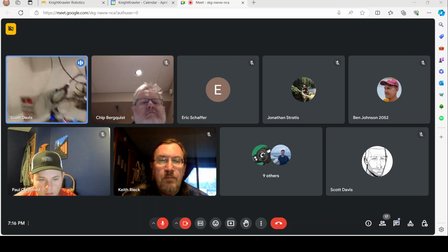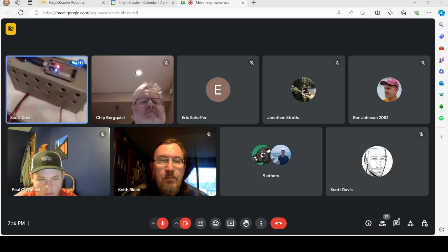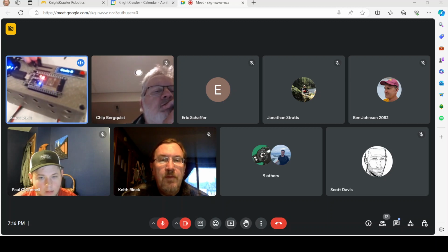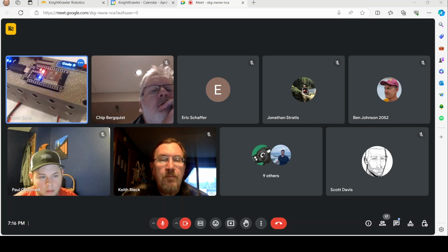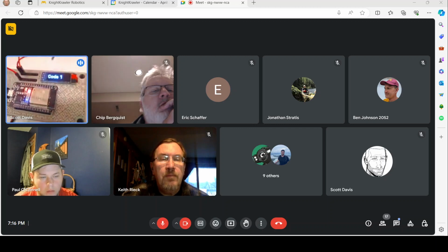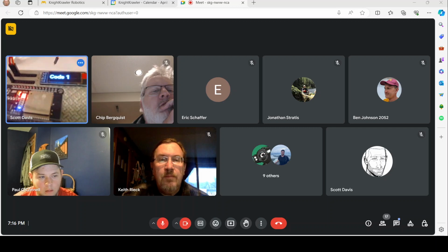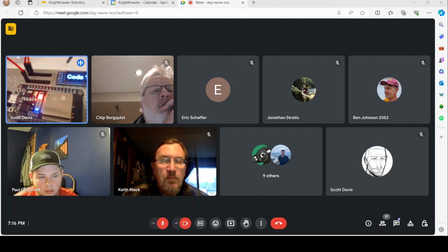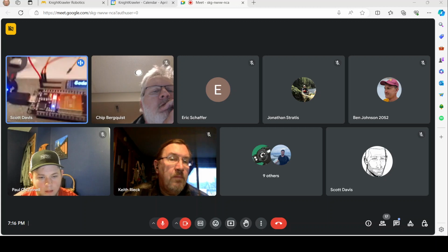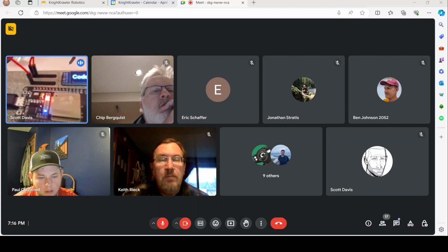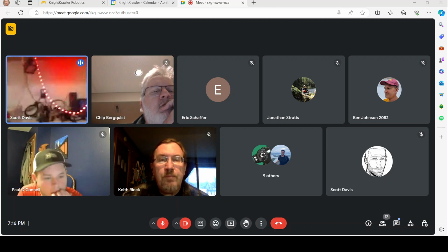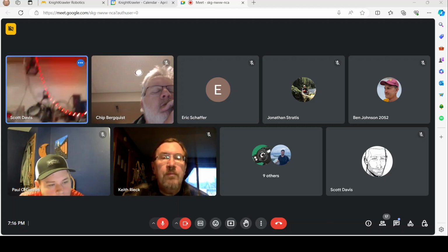Okay, so let's say that I'm going to take this first pin here. Let's see if you guys can see this. I'm going to put the first spot in the little pin header. I'm going to make it read. So there, see how it says code 1? Because I connected the first pin. So that's 2 to the 0th power, which is 1. Pin 0 is reading to ground. And so now my LED circuit is showing me lighting pattern number 1.